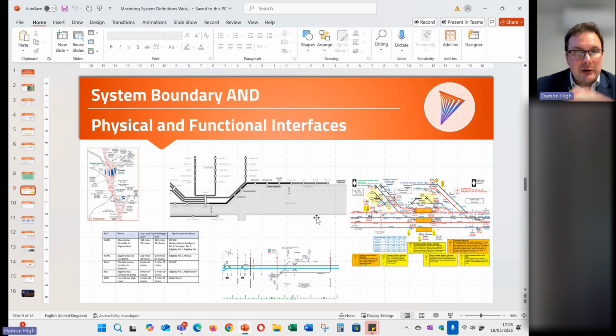So that's helping from a geographic perspective. We've got some other diagrams in here that we can use. We've got examples of some Metrolinx track maps. We've got some Network Rail track maps. You can't really see the detail too much on those, but these help identify other areas of railway, other assets, access points, footbridges, level crossings. They help identify a number of other assets that we will need to eventually start thinking about when we use this system definition to form the basis of our hazard identification activities.